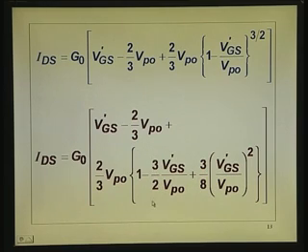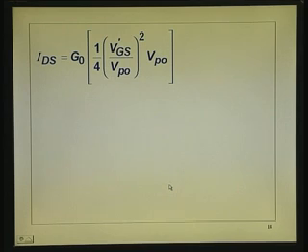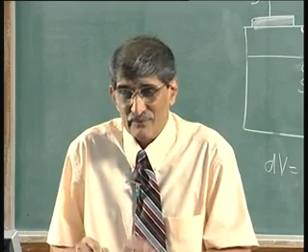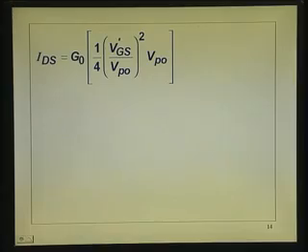So you will have this cancelling with that, nothing wrong, V_GS' cancelling with this term and this cancelling with that one. So you are left with this term, 3 goes off, 2 by 8 is 1 by 4, G naught into 1 by 4 V_P0 into V_GS' square term. Now, see, it is more pleasant to see. Plus, please remember, this is valid when V_GS' is small compared to V_P0. Very near to V_P0, it is not valid. Now, quickly finishing it off.